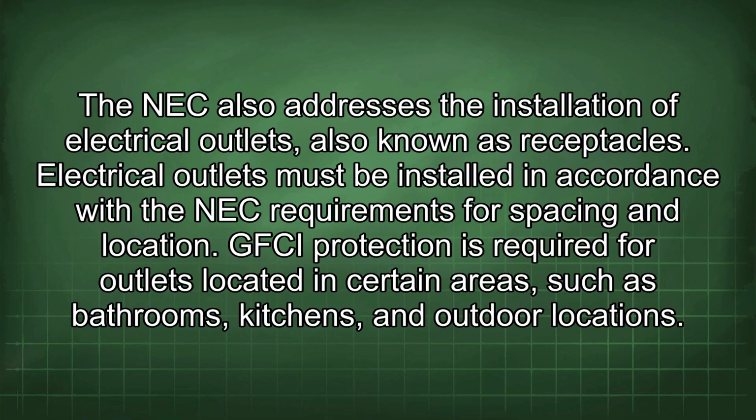The NEC also addresses the installation of electrical outlets, also known as receptacles. The electrical outlets must be installed in accordance with the NEC requirements for spacing and location. GFCI protection is required for outlets located in certain areas, such as bathrooms, kitchens, and outdoor locations.